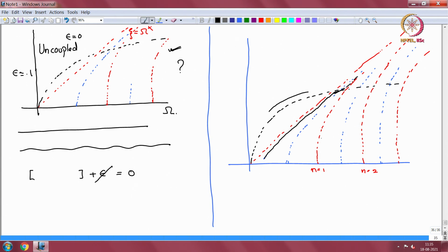So I will show it more clearly here. So this rigid duct cut-on will become this black line over here, okay, and as we approach this flexural wave line, it turns and then it crosses at a certain point. So below this frequency it is below the flexural wave, above this frequency it is above the flexural wave, and then it starts to follow the next higher rigid duct cut-on asymptotically. So this red fellow will become this black line.